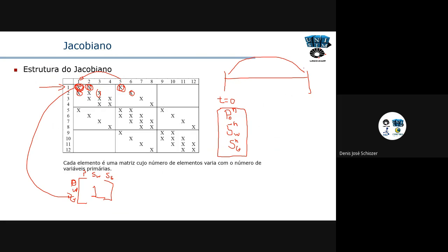And let's assume that this is a time step. When I'm solving this equation, let's assume that I'm using 30 days as the time step. Solving this equation means that I want to know the pressure, saturation of water, and saturation of gas at what we call n+1 here. n+1 here is 30 days, okay?